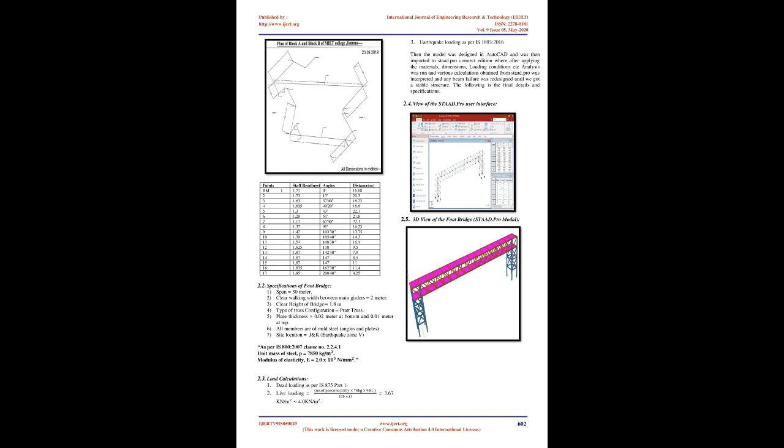From model generation, analysis, and design to visualization and result verification, STAAD.pro is the professional's choice for steel, concrete, timber, aluminum, and cold-formed steel design of low and high-rise buildings, culverts, petrochemical plants, tunnels, bridges, piles and much more. To perform an accurate analysis, a structural engineer must determine such information: structural loads, geometry, support conditions, and materials properties. The results of such an analysis typically include support reactions, stresses and displacements. This information is then compared to criteria that indicate the conditions of failure. Advanced structural analysis may examine dynamic response, stability, and nonlinear behavior.